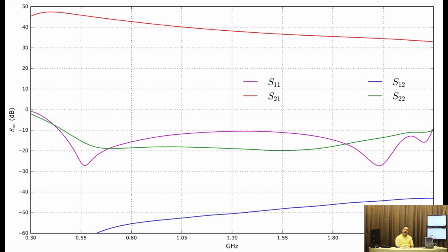So when one adds a third stage, typically a designer would try to design an interstage matching network such that it has a high pass nature. It means it would attenuate your signal at low frequencies, but it would add gain to your signal at high frequencies. So if you superimpose these two together, you will achieve the desired gain flatness in your overall amplifier unit.